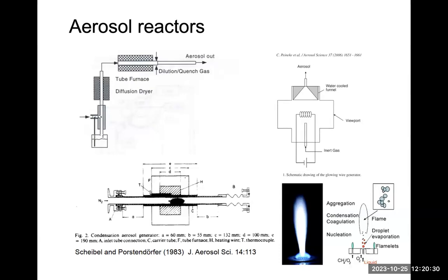They get into the gas phase, and when they get out of the furnace, people can add on this dilution section, which reduces the pressure but at the same time maintains relatively high supersaturation for the ammonium sulfate, ammonium nitrate. Then these vapors nucleate and form particles. You can control the dilution process to minimize the size of these ammonium sulfate particles. Their sizes after this nucleation and initial stage of coagulation and condensation will be much smaller compared to the method where they're generated from the nebulizer directly.